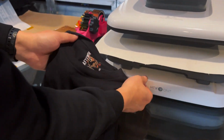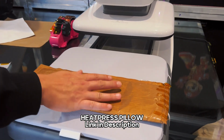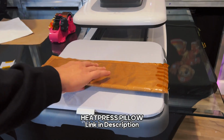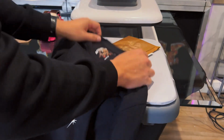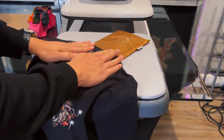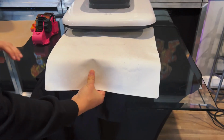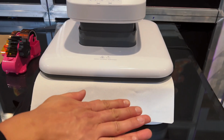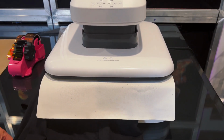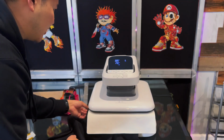Okay, that worked, but let me show you what I would recommend. So I would recommend getting one of these heat press pillow packs. You can get a 5-pack off of Amazon. I think it's like less than $20, different sizes here. This is the proper way to do it. All you need to do is put that pad right in the middle. It makes it nice and flat. So afterwards, you can just put any kind of padding on top of it or finishing sheet and then just finish it off with the press. Now when it squeezes flat, it is nice and flat so that you're gonna get even pressure all around, much better results. You're not gonna have edges that are gonna be lifting off.